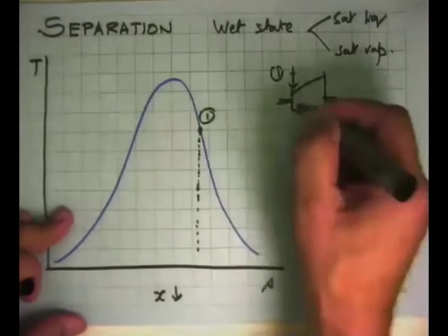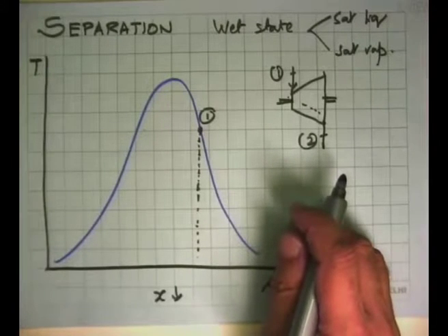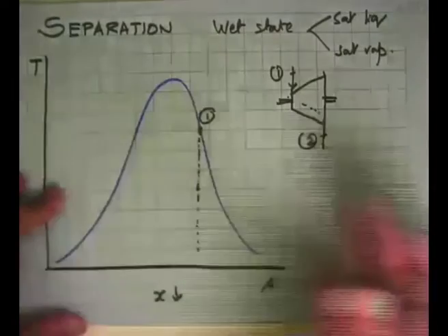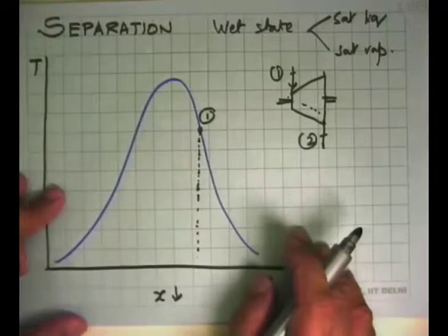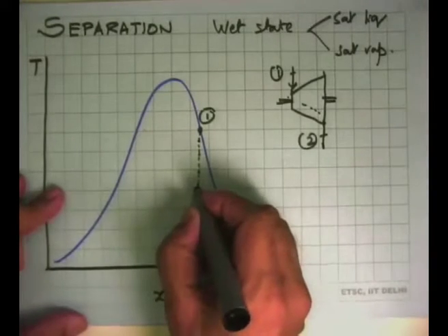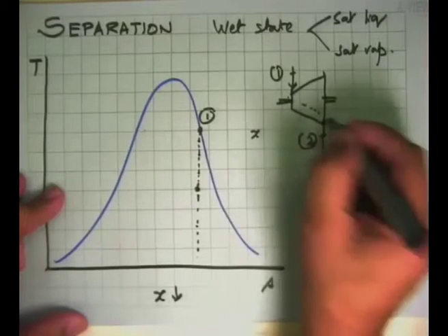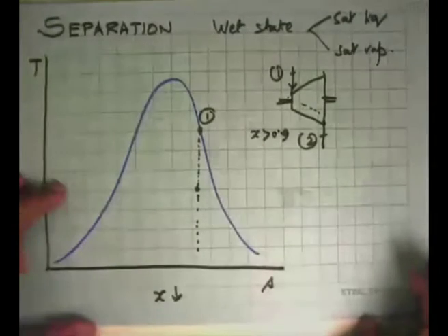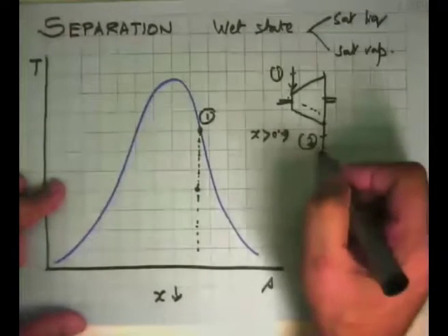Which means that the amount of liquid flowing in the turbine is increasing, and this is largely dispersed as very small drops, and they can go and hit the blades. They don't follow the same expansion laws that vapors follow, so the design and engineering of this type of machine becomes practically impossible. So what one does is say, okay, I can make a machine with an exit dryness fraction of more than, say, 0.9. So I can design a turbine and it's reliable up to this point. So at 0.9 we take it out.